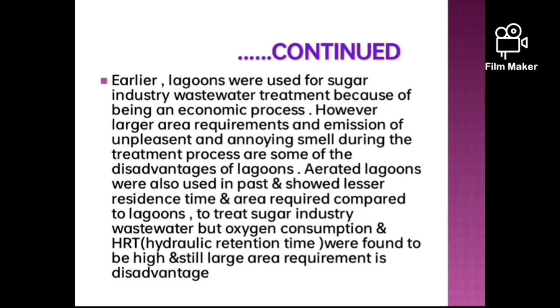Aerated lagoons were also used in the past and showed lesser residence time and area required compared to lagoons to treat sugar industry wastewater, but oxygen consumption and HRT, that is hydraulic retention time, were found to be high, and still large area requirement is a disadvantage.